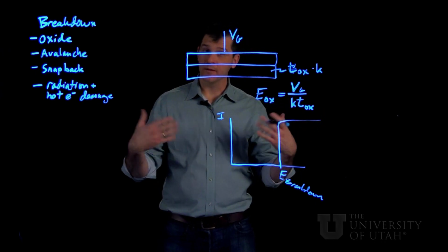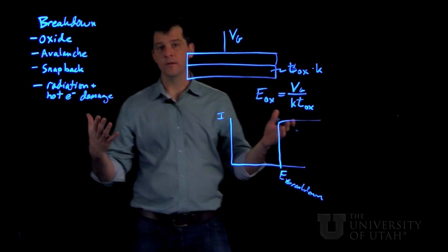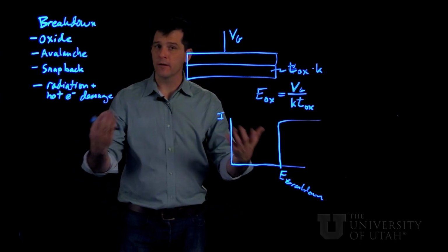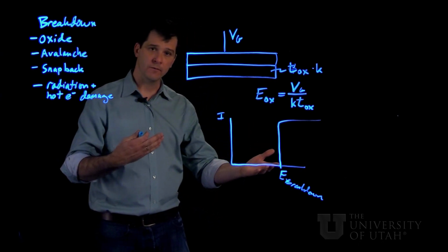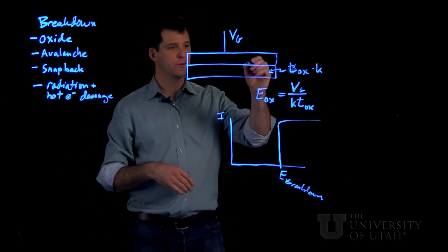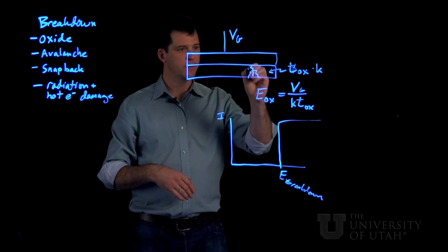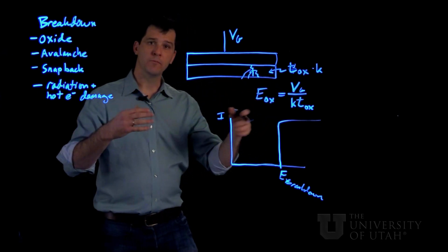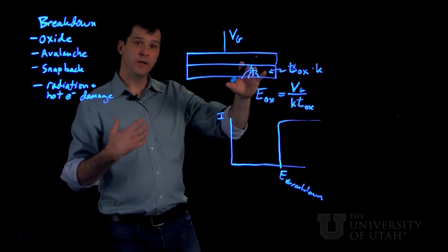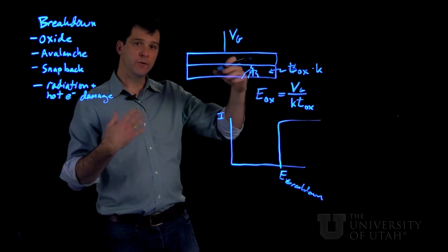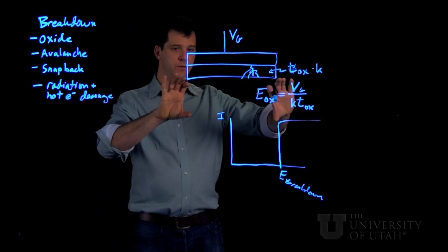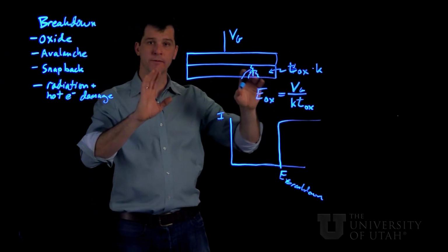And this is the same phenomenon that you see when you scuff your feet on the rug and then touch a doorknob. The air has a certain dielectric breakdown strength, and so does an oxide layer. So literally lightning bolts start shooting through this dielectric, and you get parasitic conduction through the oxide, and you will tend to reduce your amount of charge control in the channel under the oxide, as well as inducing unwanted leakage currents.